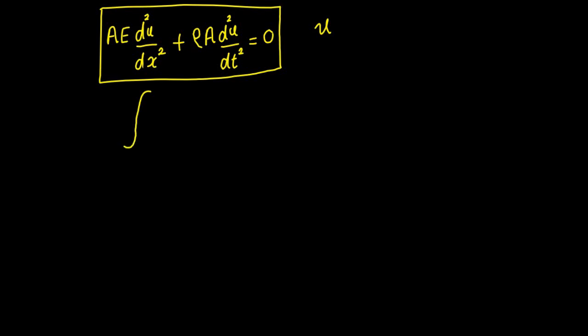So what is Galerkin's weighted residual method saying? Integral of w into r into dx should be equal to 0. That is Galerkin's weighted residual method statement. So if you have some kind of trial solution that you can assume, and if you plug it in after differentiating it 2 times, the right hand side should be equal to 0. If it is not equal to 0, we say that there is a residual error, r. So we know what r is. It's simply the governing differential equation.